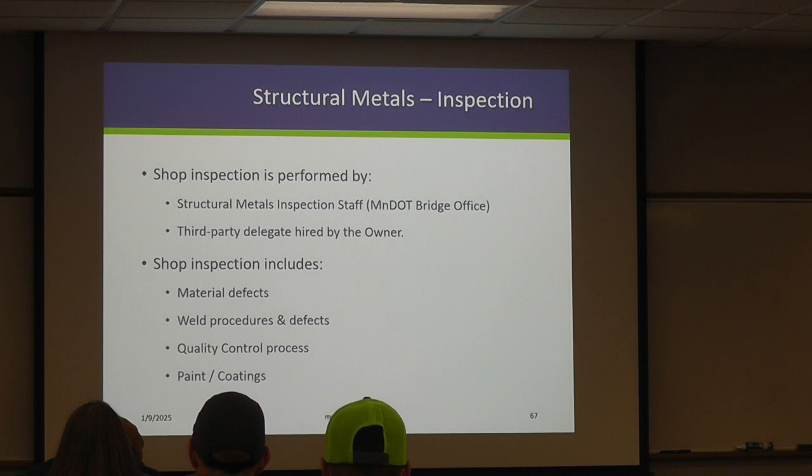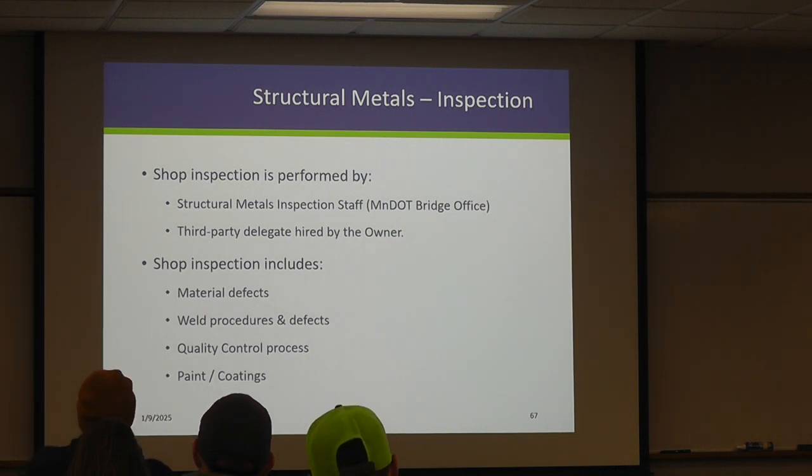Okay. So once all of these things have taken place, and coatings are part of the fabrication process, just to keep that in mind, this material is going to be inspected by shop inspectors. So if it's a MnDOT project, it's our structural metals staff. If it's a local project, it may be MnDOT structural metals, it may be a third-party delegate that's going to be hired by that owner.